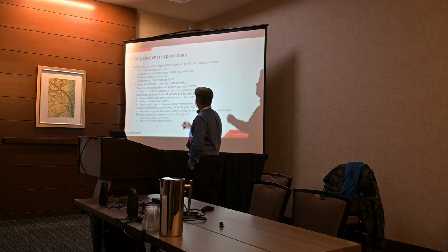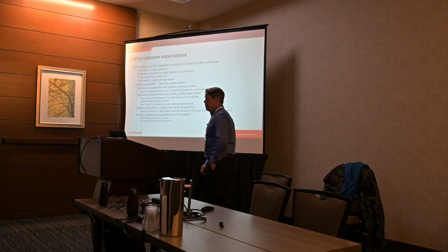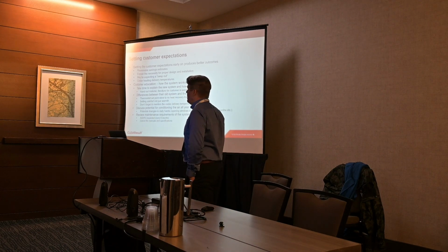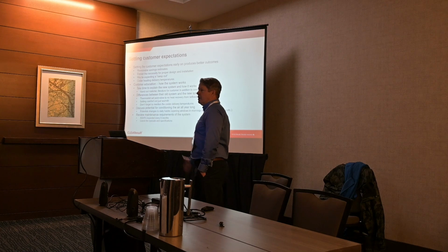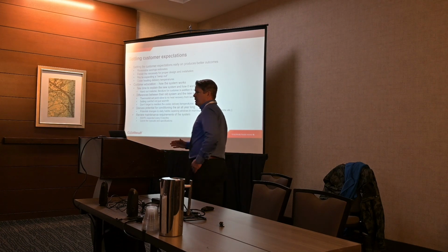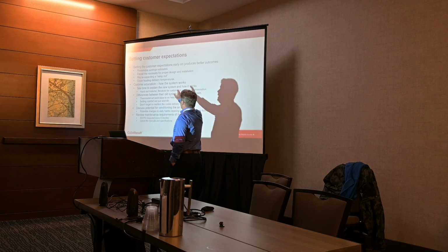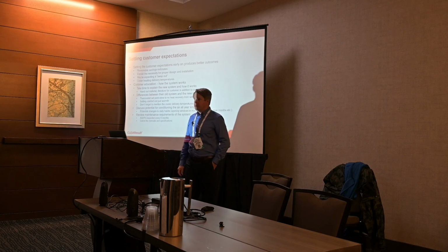right? Sometimes customers think this is going to be a simple swap out. 20 years ago, my HVAC guy came out, he took out my old furnace, he stuck a new one there. 20 years later, we're still good, right? That's not going to work with the heat pump. It's probably not going to be a swap out. That'd be pretty unusual. Again, mention the cooler delivery temperatures, okay?